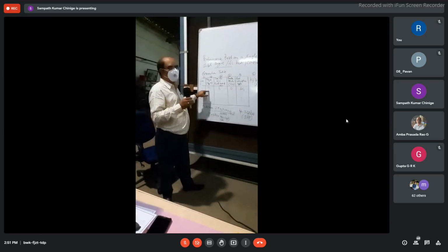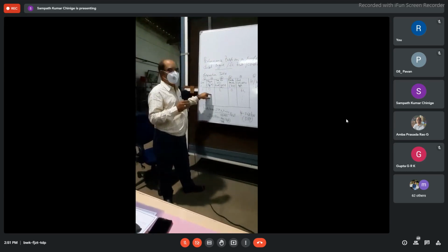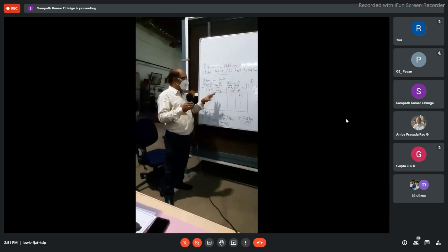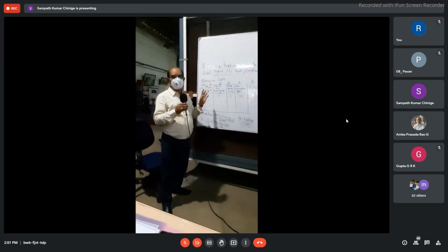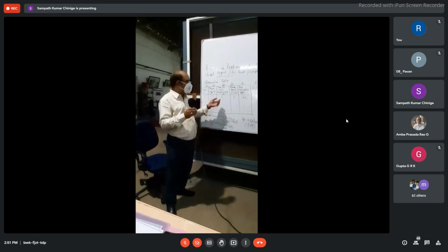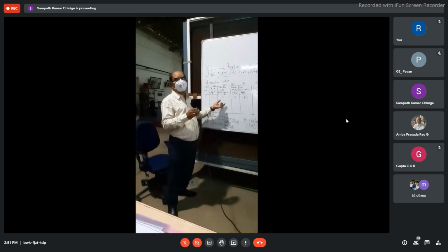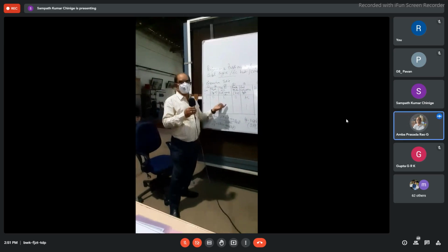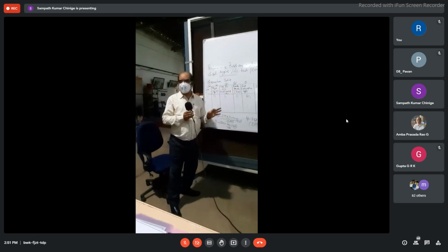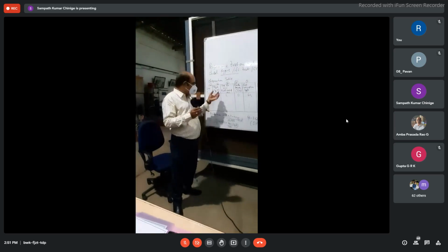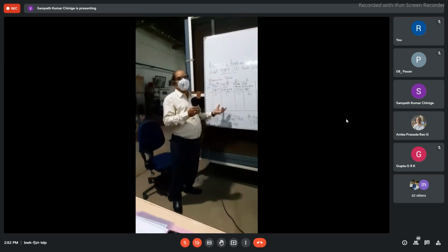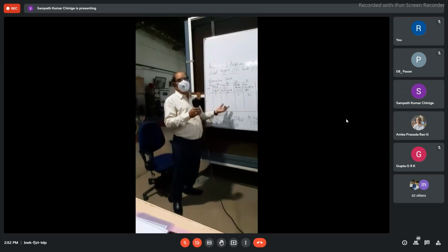By adjusting the fuel, you get it to 0.5. Once we load the engine from an external source, through resistances and a DC shunt dynamometer, the engine speed will fall, and you compensate for the loss in speed by adjusting the fuel rack so that the engine is again brought to 1500 rpm. Allow the engine to run for some more time so that it is steadily running at 1500 rpm. Irrespective of the torque meter reading, every time you have to bring the engine to 1500 rpm, noting down the time taken in each case.